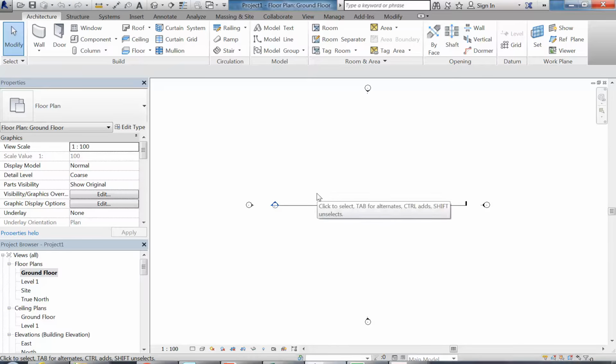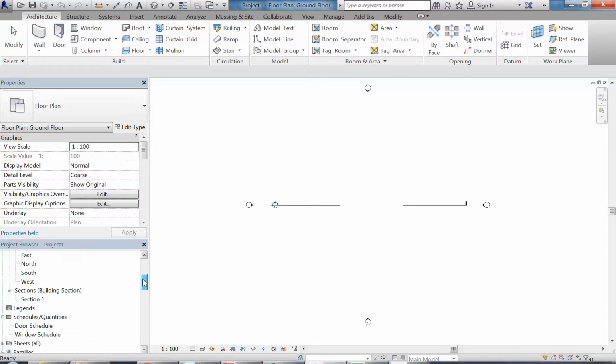Okay, so now ready to bring this into AutoCAD. From AutoCAD into Revit. So I'll show you a couple of other little tricks as well. If you know that you have multiple levels and you're going to make a basement level that's not entirely below the ground, it sometimes helps to turn the ground floor into your basement.